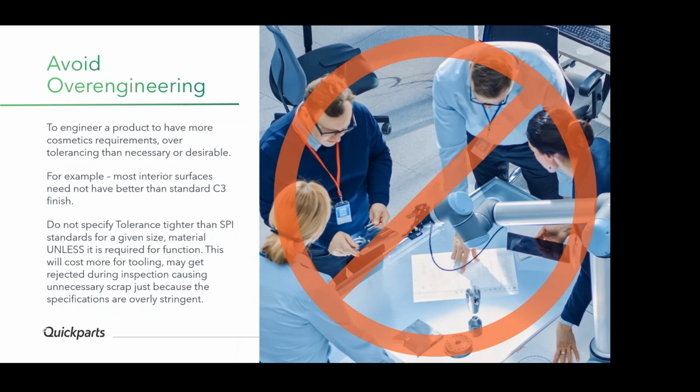I would say avoid over engineering is just part of part design, right? When you design a part, you also add tolerances, specifications, create a 2D drawing. On that 2D drawing, just make sure you don't specify too tight tolerances, and choose finishes that are unnecessarily expensive.